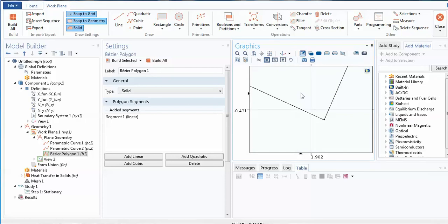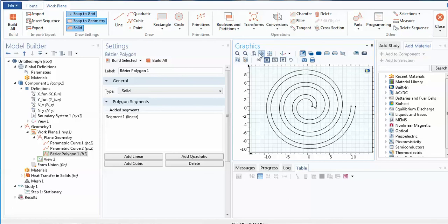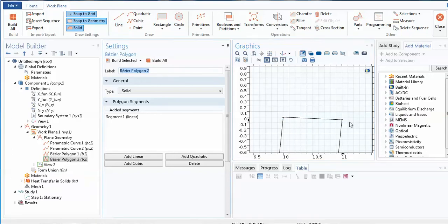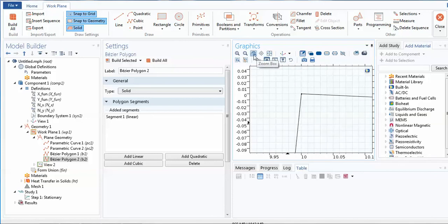So I'll zoom it to the extent that it is connected, and similarly I can use the Bezier polygon option to the another end. I go to this end. So the better option is to locally zoom it. Then I click on the line and go to this point, click it, then go to this point, click it, and press right click to stop it. So I think this is also clear. And similarly I will check, if it does not give the 3-dimensional geometry, then obviously one of the reasons may be that it has not been connected properly if you are using the manual option. Otherwise, using mathematics, using a proper function, even with correction, such a problem will not occur.